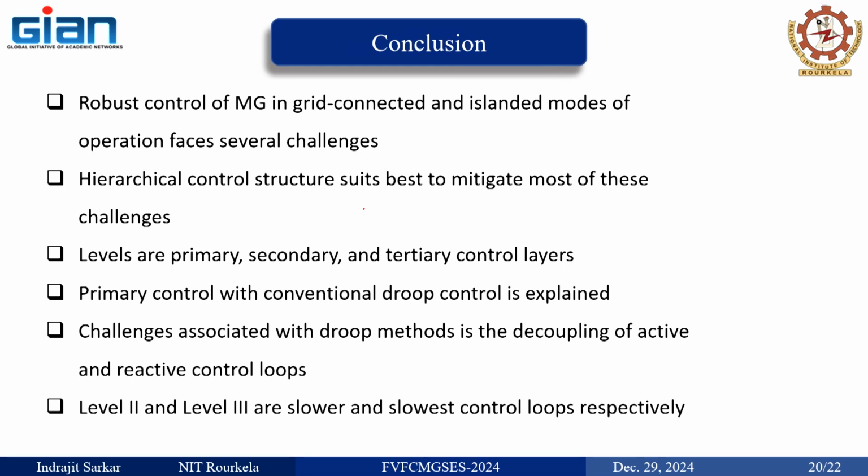So I also proposed one work which one PhD student will work on, where there will be microgrids with hierarchical control and they will communicate with each other. When microgrids communicate with each other, it is at the upper level, the tertiary level. There is a communication link needed in between so that they can communicate about their active and reactive power demand at the individual level. Accordingly they can fetch and deliver to the grid. So tertiary level control will communicate between the different microgrids.